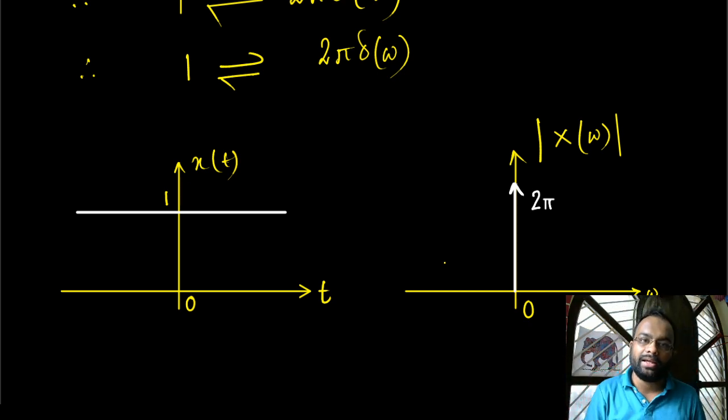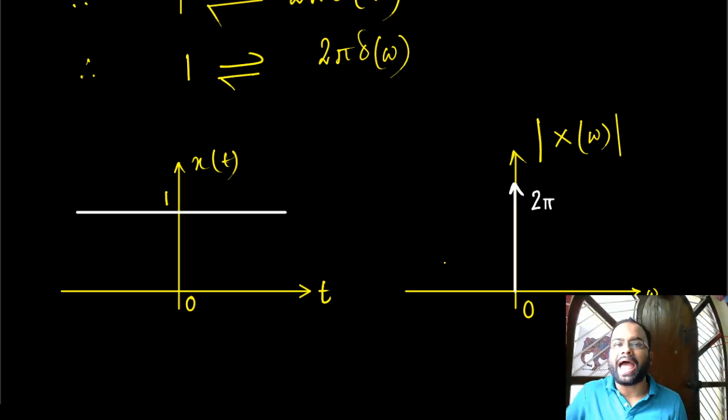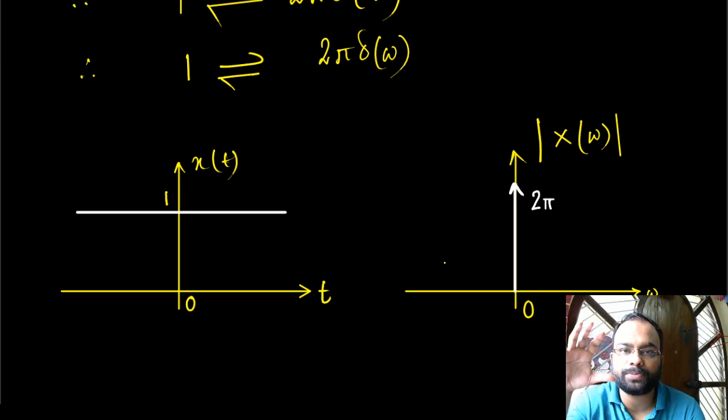With that said, that's the total discussion here today. We are going to end the discussion today because we had plenty of other agenda, but we shall continue that in the next class. I believe you understood the idea behind this. By doing Fourier transform, you can see the internal composition of the signal. From the perspective of the system, exciting a system with an impulse is like exciting the system with every possible frequency. That is why the impulse response of our linear time invariant system encapsulates the entire behavior of the system. We discussed quite a few important interesting things here.